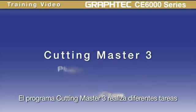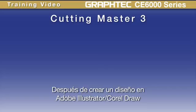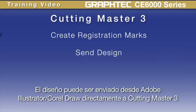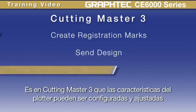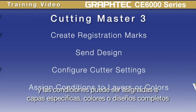The Cutting Master 3 application does several tasks. After creating a design in Adobe Illustrator or CorelDRAW, registration marks for the print and cut process can be placed on the job design. The design can be sent from Adobe Illustrator or CorelDRAW directly to the Cutting Master 3 application through the special GraphTech plugin that is added to Adobe Illustrator and CorelDRAW. It is in Cutting Master 3 that cutter settings can be configured and adjusted. And conditions can be assigned to specific layers, colors, or whole job designs.